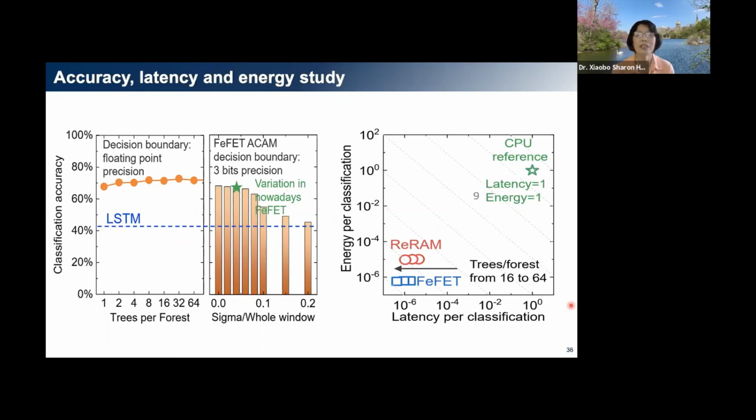What is the manifestation of device nonlinearities in FeFET memory? Random bit flips, stuck-at faults, they're different. Okay, so what type of non-idealities? So I talk about the variations. Random bit flips, this would depend on temperature effect, you might have random bit flips. And actually, these are all very good questions. Radiation effect, temperature effect, and also reliability, in terms of retention when you use the data for a while. These are all effects that could impact the behavior or the storage.